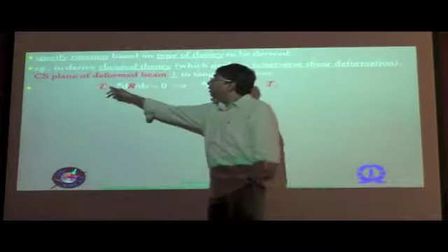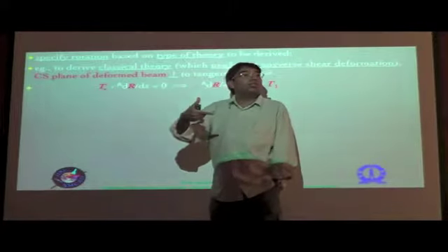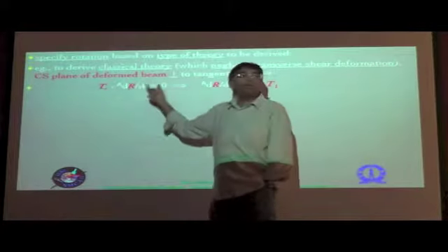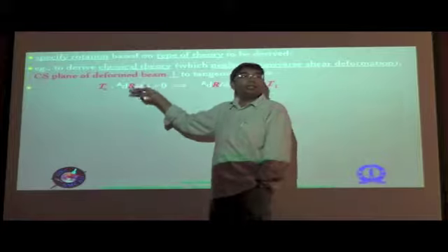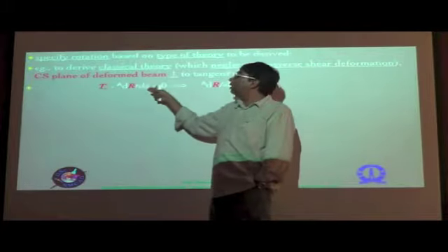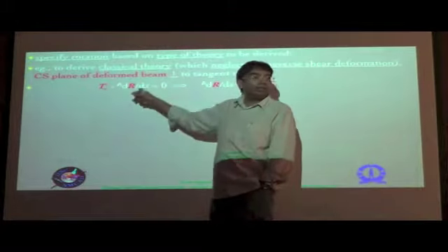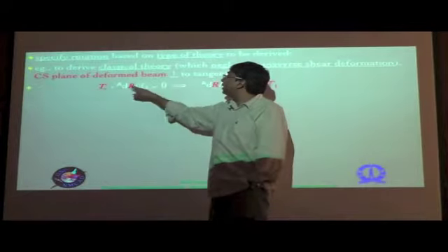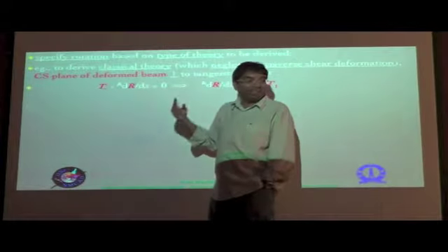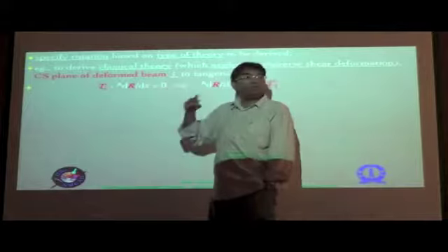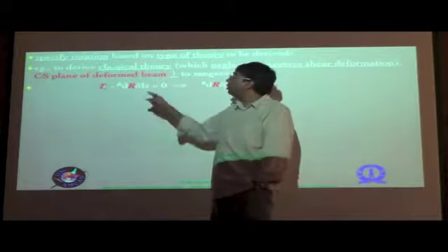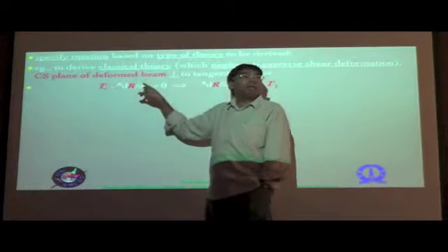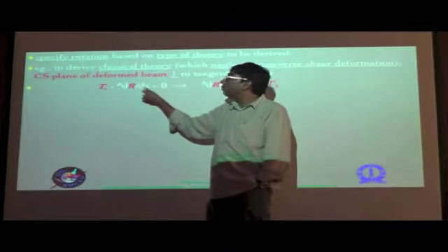So basically, in other words, your T2 and T3, which are in the cross sectional plane, will be perpendicular to the tangent. The tangent is nothing but the derivative of the position vector with respect to the arc length in the deformed configuration. So in this case, it's basically dR by ds, rather than in the small r case, where it was dr by dx1, which we could have just written as small r prime. But here it is not so, it is dR by ds.